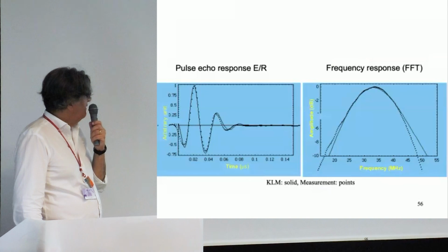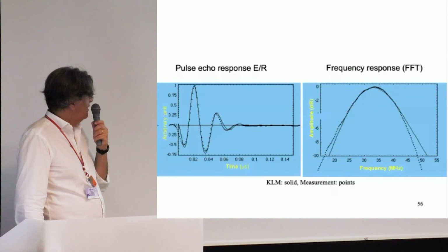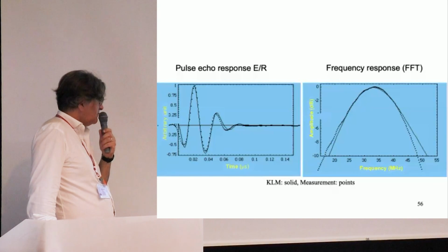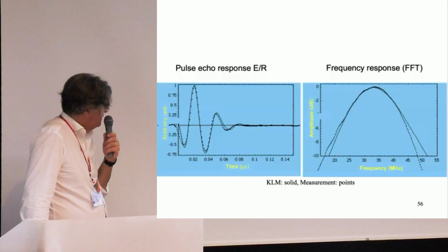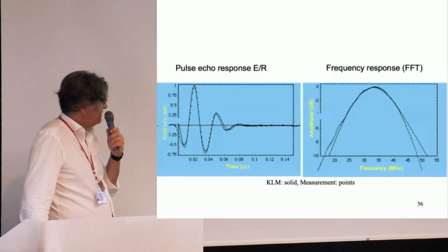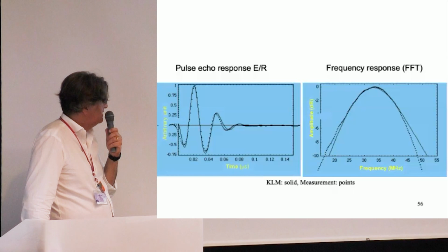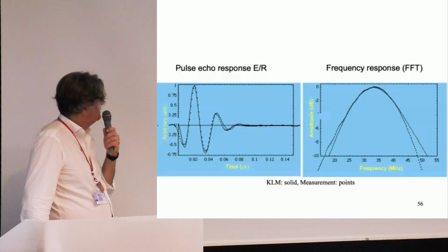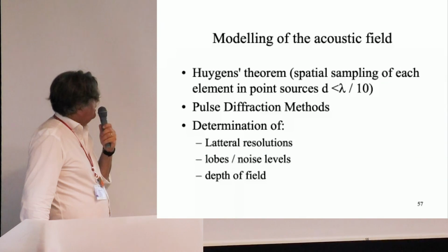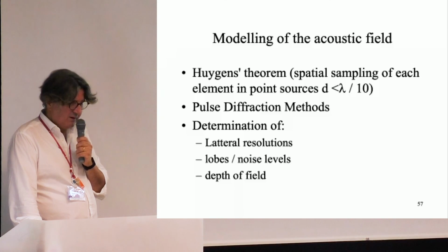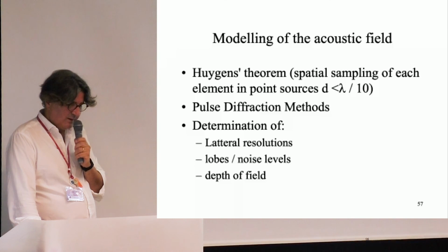For instance, here you have the pulse echo response, with simulation and experiment, of a 35 megahertz transducer. In terms of sensitivity also, you can see that it is quite nice. You can also do some modeling of the acoustic field using Huygens' theorem.